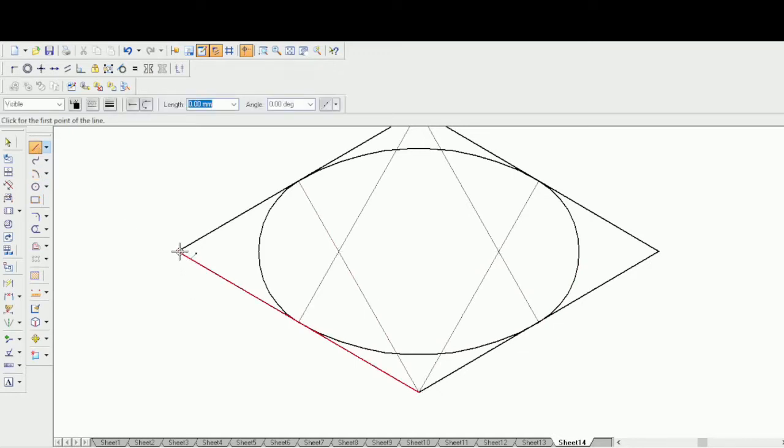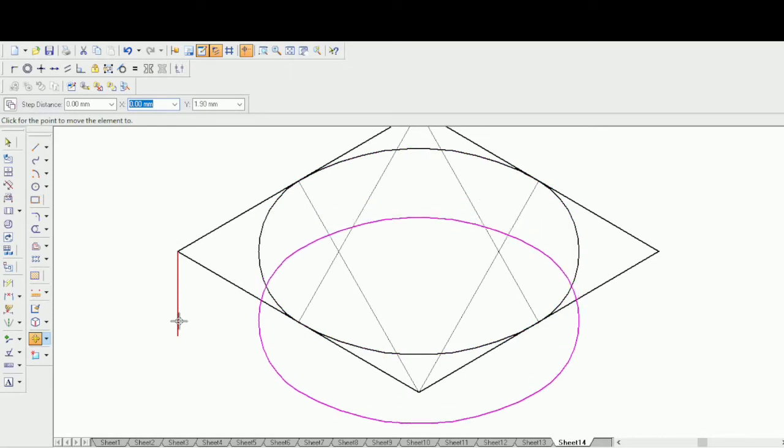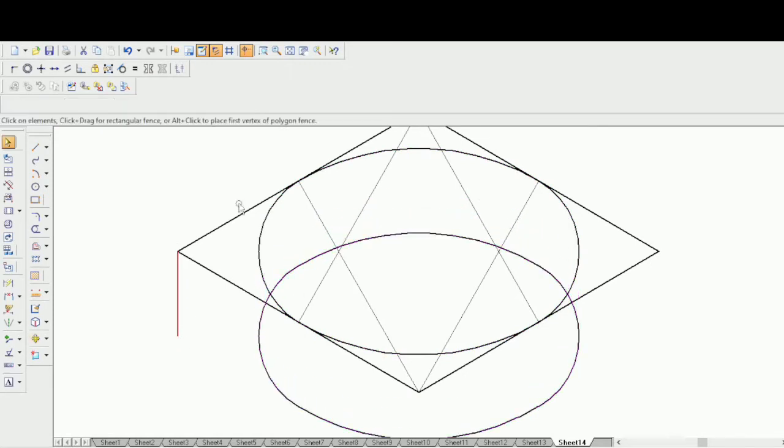Now let's go to a visible line. So from here, let me give its thickness. Its thickness is given as 30 here, so just enter. Now, to create the cylindrical slab, let's select these 4 arcs. Pressing the Control key, let's select all these 4 arcs. Now let's move that with copy switched on. So here you click this point, left click and drag it till here.